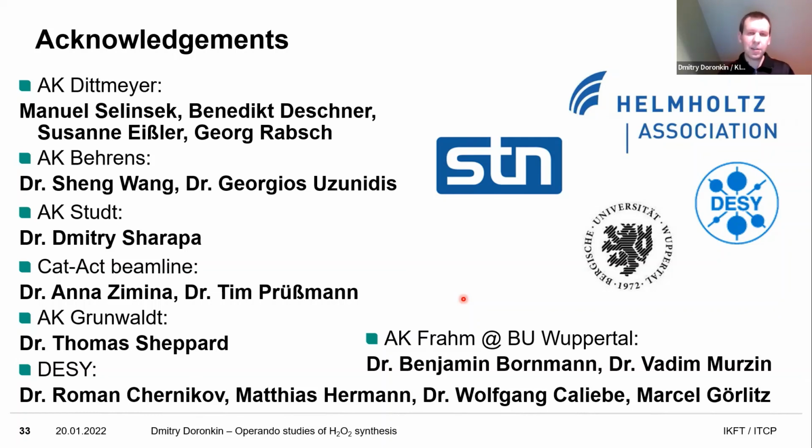And the limiting factor for this maximum temperature, again, is the mechanical stability of PEEK at 100 bar, which was calculated, and it starts basically flowing out. So it becomes too soft to hold 100 bar above 100 degrees C.